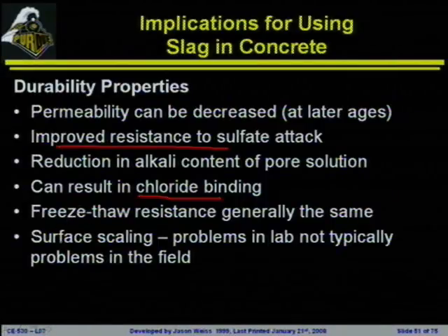One of the other things that I will mention here, and we'll come back to this: a lot of the materials that we will talk about that have supplementary materials will show a problem with scaling, especially in the lab. This is the top surface, the top film of the concrete, coming off when it's exposed to freezing and thawing and de-icing salts. You'll see that top thin surface will pop off.